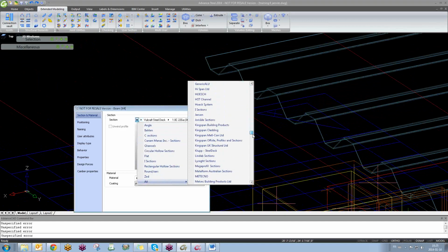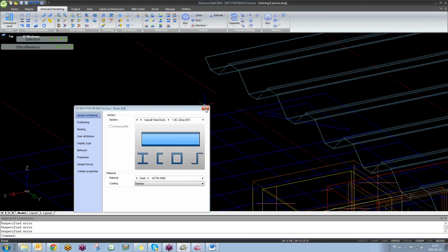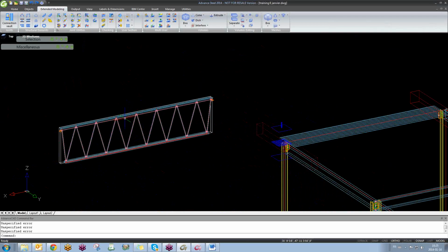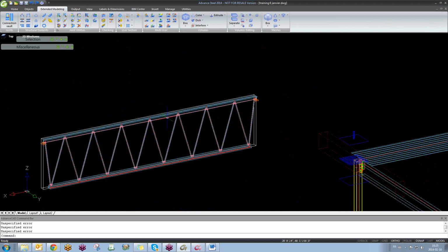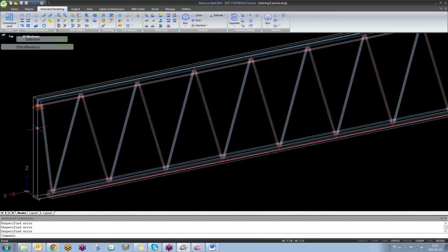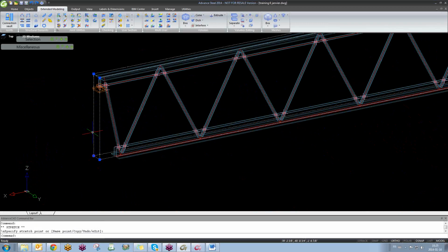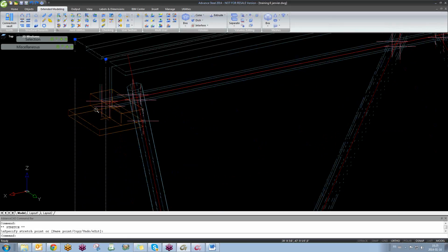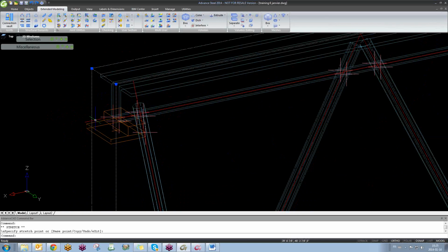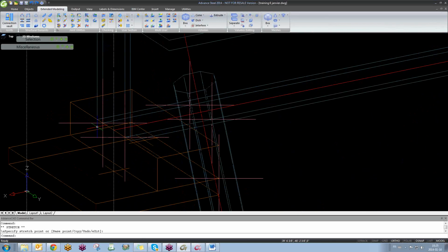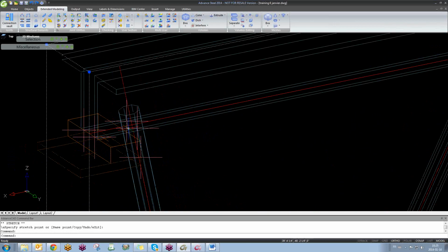Well, you have this extensive library, and as I said, once the profile is here, it means that it's saved under the library. That's it. Okay. So let's say, for instance, if I cut that section, so it's already putting a joist seat on there and everything, huh? Zoom in on that joist seat on that end there. Let me see that. Here? Yeah. You can absolutely customize that. You can absolutely play with the shape of those plates here. Right.